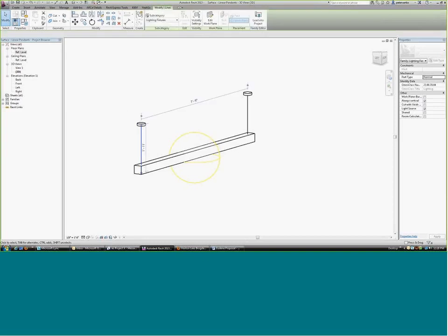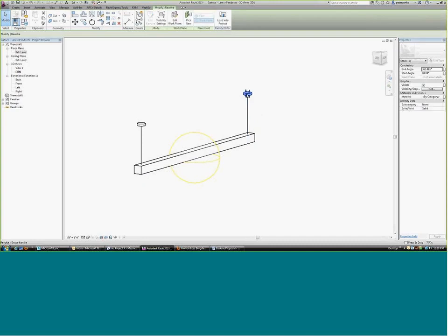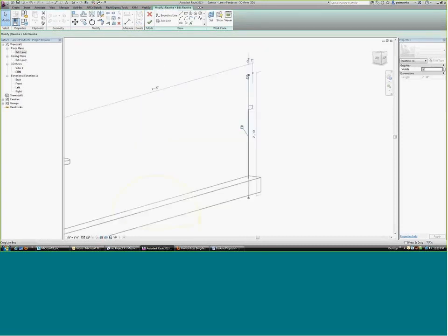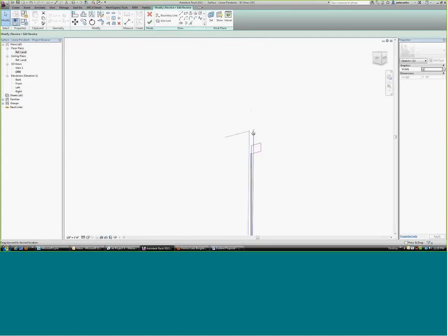Did you change what changed so that it won't show up in floor plan again? The escutcheons that are on the ceiling. I selected one, edit revolve, and there's an axis that it revolves around, and I made sure that it doesn't really extend much below the fixture.